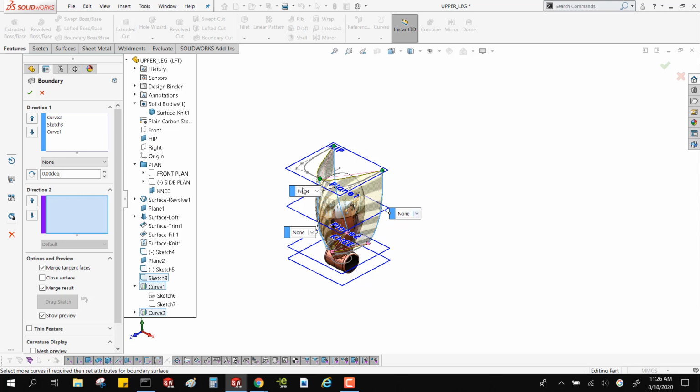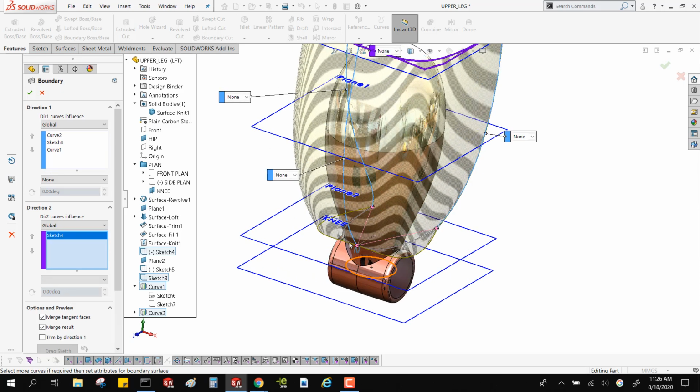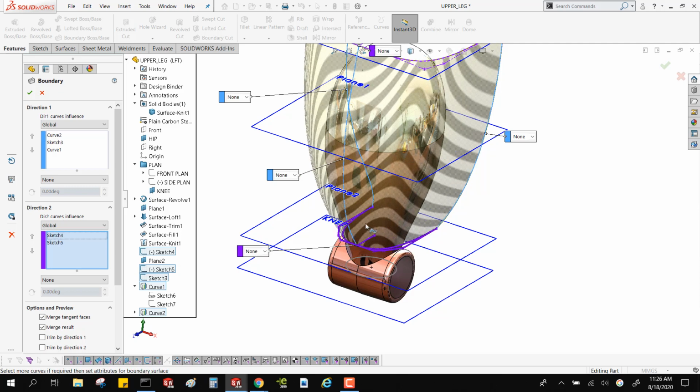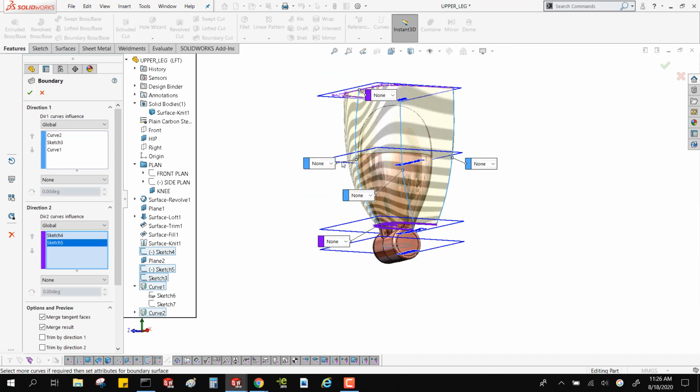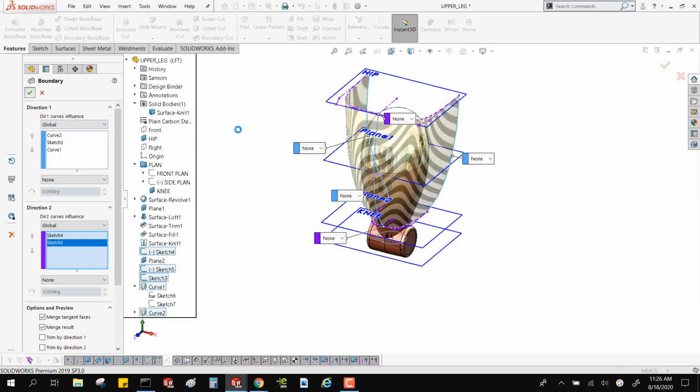Also, when you've got a shape like this, I was talking a little earlier about when I had that circle and that ellipse. If I had guide curves on all four sides, it's a better idea to do the guide curves because you're not going to accidentally get that twist happening. If you use the ellipse or the circle as the guide curve instead of the actual cross section, usually you have better luck with that. But there you go, a nice smooth squared off front.